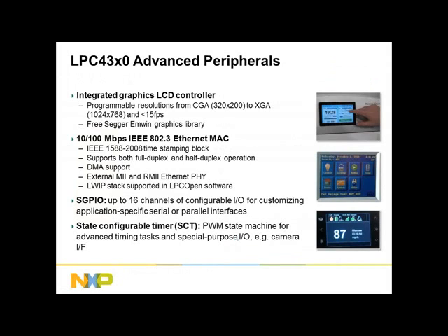Another advanced peripheral is the LCD controller. It's a graphic LCD controller on the 4370. If you wanted to interface to a color display, you can do it through this graphic controller. We can go up to 1024 by 768 resolution. I would say typically people use smaller resolutions when we have customers design this in. It's the same IP that's on our very successful 1788, our 8X family and 4088. It is also on our 4350 and our 1850.